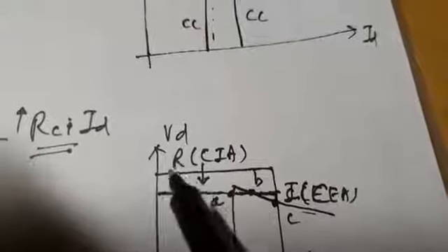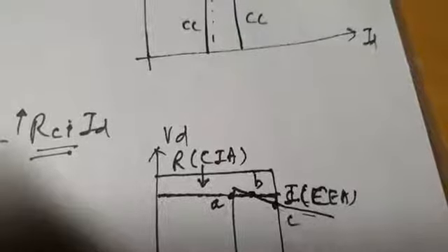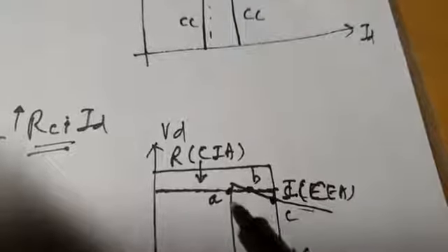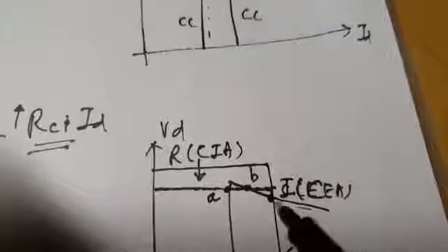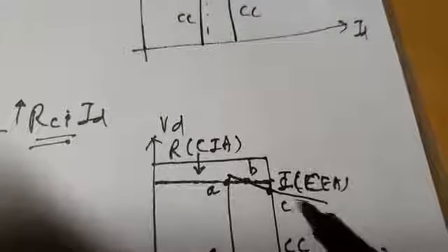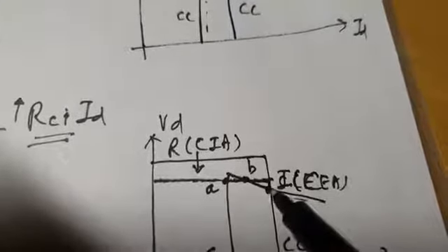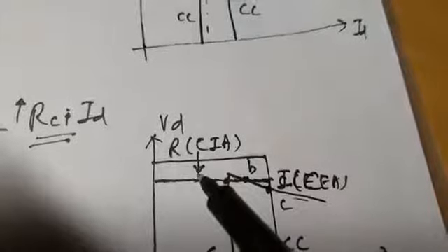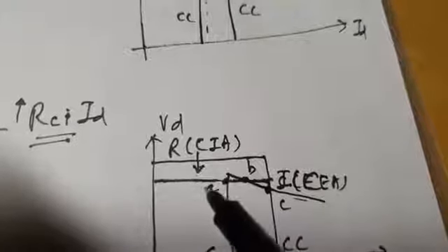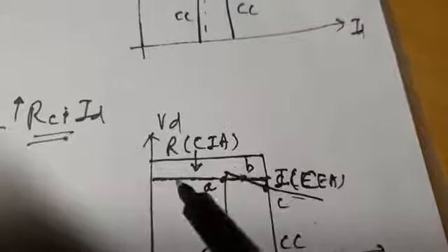This was the earlier rectifier side characteristic, and this was the inverter characteristic. Because of a fault on the inverter side, it became more drooping, more slopey in nature. But the point of intersection is still this. Now suppose due to some fault the rectifier characteristic also drops, from this to this.